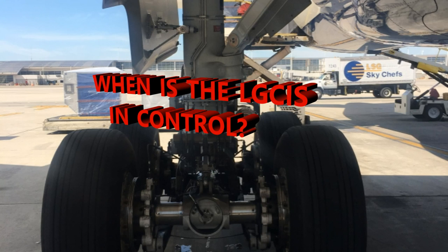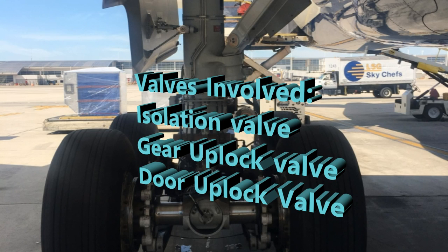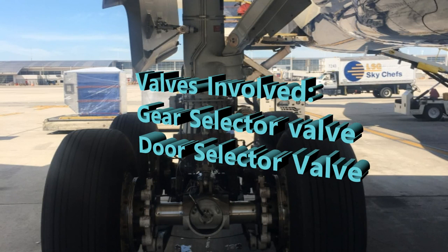All right, now what about the different valves that are involved with the landing gear extension retraction system? There's going to be your isolation valve, that's just isolating the hydraulic circuit from the normal supply, and here we're talking about the extension retraction, and then gear up lock and door up lock, and your gear selector as well as your door selector valves.